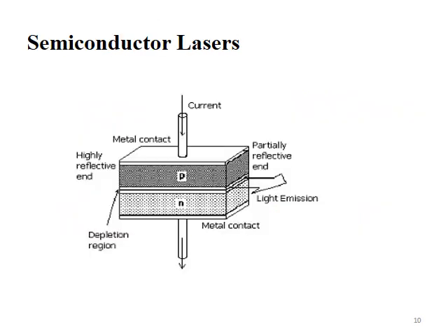Last one is semiconductor laser, which is nothing but a PN junction laser. A semiconductor laser is a specially fabricated PN junction device which emits coherent light when it is forward biased. It is made from gallium arsenide, which is operated at lower temperature and emits light in the near IR region. Now the semiconductor lasers are also made to emit light almost across the spectrum from UV to IR using different semiconductor materials.